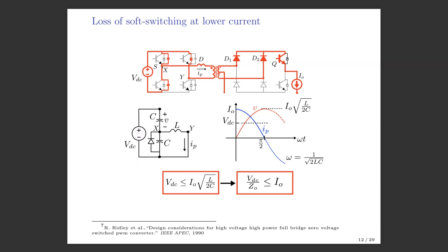Now, what will happen to this voltage, the X voltage? It will start becoming less than the receiver's voltage. So what will happen to the XY voltage? It will start becoming negative because Y is still at VDC and X is falling from VDC. So it will become negative. If this diode is conducting, here the voltage is negative, here also the voltage will become negative. So across this diode, the voltage will start becoming negative. And if the voltage becomes negative across this diode, it will forward bias this diode D2.